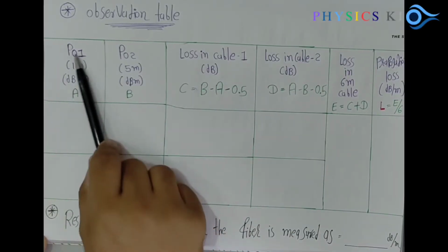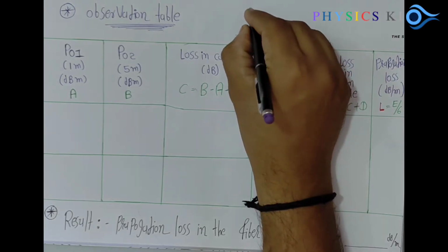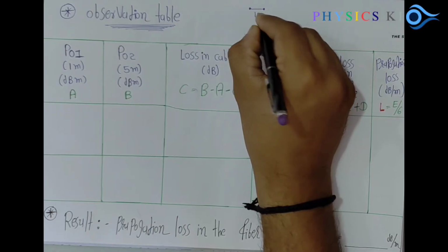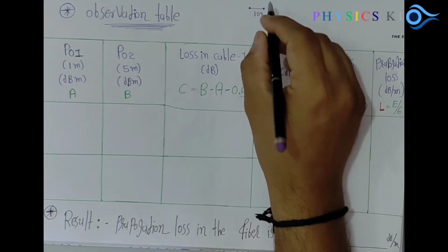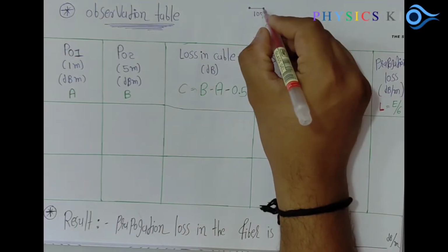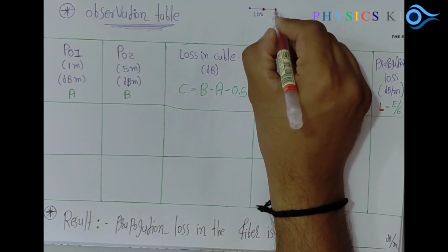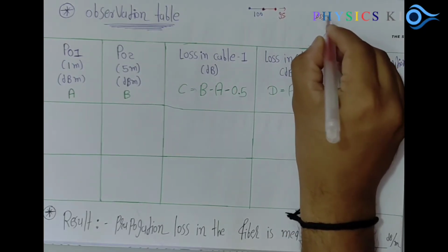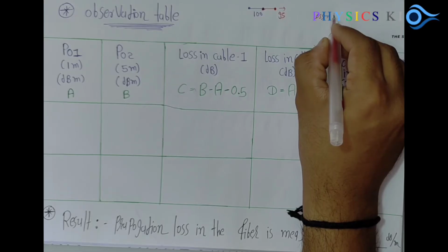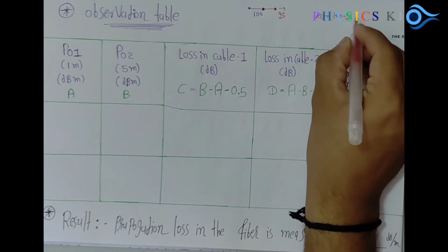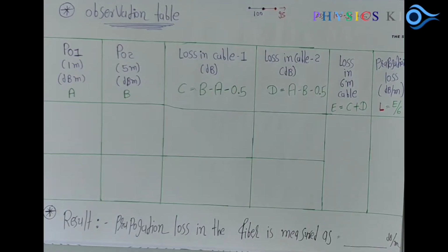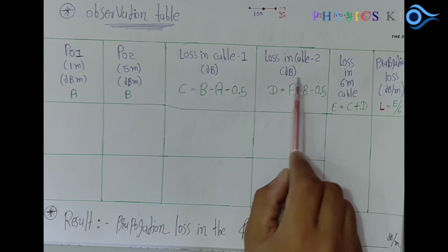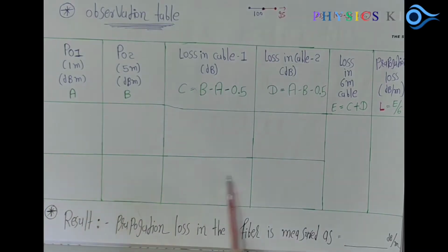And how to measure the loss, we have a simple terminology. Let's see, this one is one cable. Suppose the output of this cable is 100, okay, and now after that I connect the second one, this red one, and the output of this red one is 95. So how much is my loss? 100 minus 95, so the remaining value is only 5. So 5 is the loss of this particular connection. The same terminology we can apply to this experiment setup.